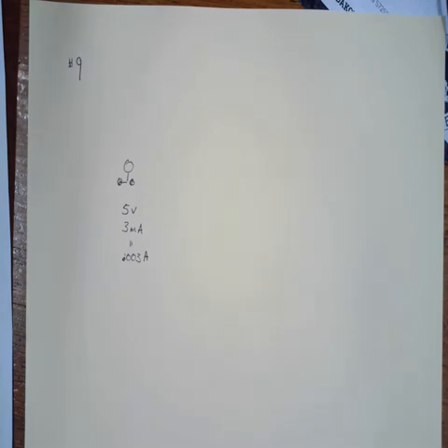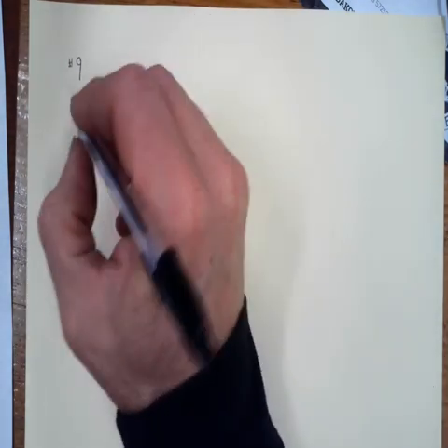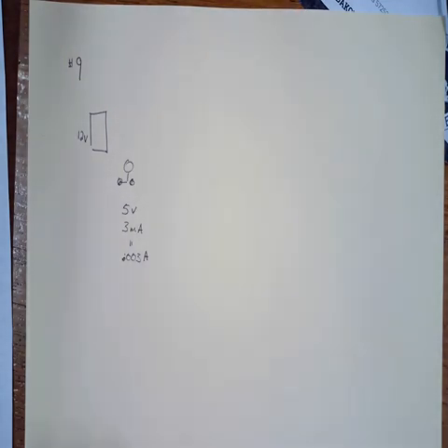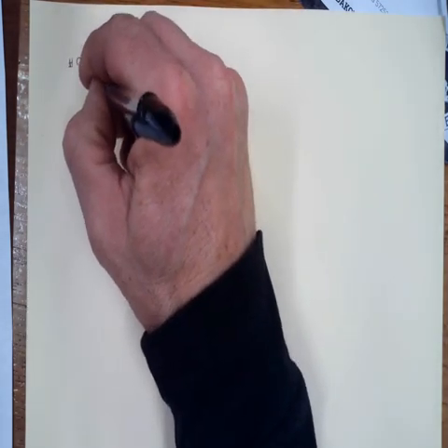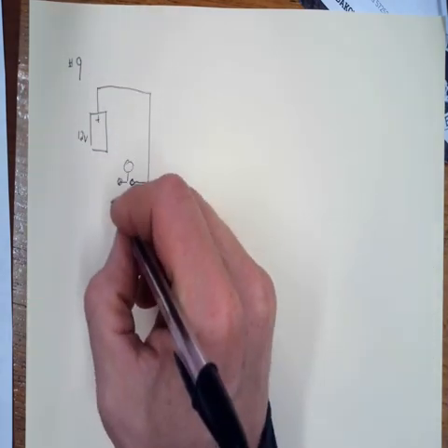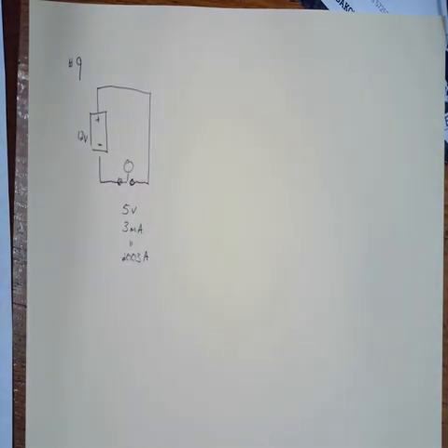So this is actually really common, and the problem in this particular circuit is that it's an automotive circuit, so it is always at 12 volts. So this lamp is going to be involved in our automotive circuit, but if we supply 12 volts to this LED, it is going to burn the LED out. It's too much electrical pressure for it.